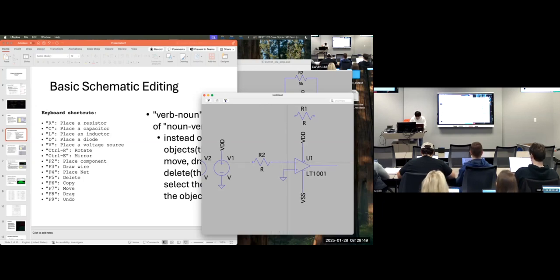So one wire here, one wire. Let's just put it right here. Press escape, and now let's do our negative feedback. So I'm gonna go in between R2 and R1, go up here. Click. Boom. As you can see, whenever there is a node, it automatically creates a little node for us. So that's a nice indicator showing that we have created a node.